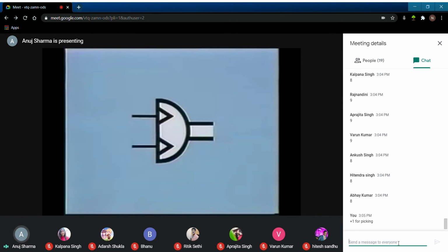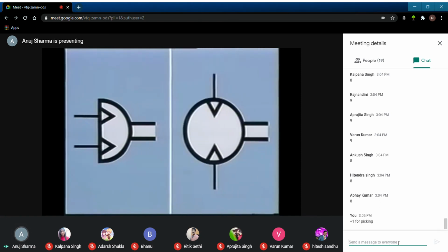This is the symbol for a rotary actuator with a limited angle of rotation. A different symbol is used to represent rotary actuators with unlimited rotation called pneumatic motors. These are a good example of how symbols reflect component function rather than structure.